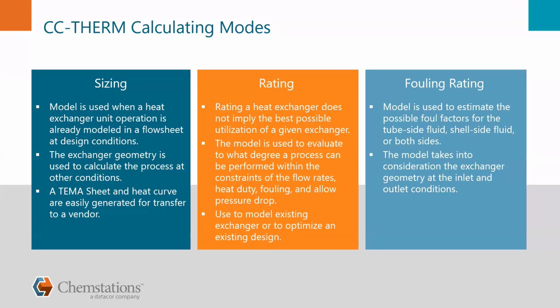How would you know? If you overestimate this value, you will be cleaning this heat exchanger too often, so the cost of maintenance will go high. If you underestimate, then this heat exchanger will foul a lot. Then it will not be cleaned, so it will not be as efficient as it should be. So it will be fouling faster. So finding the correct fouling factors, or using something that is more efficient for your system, is actually quite good.